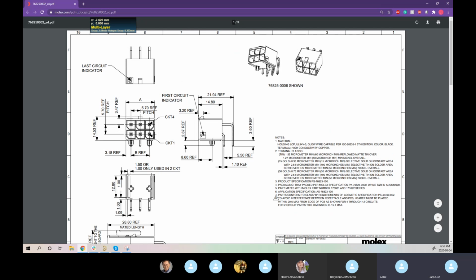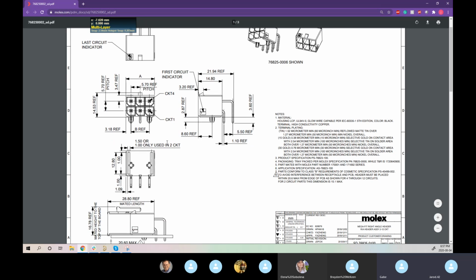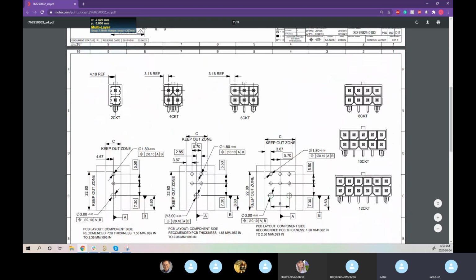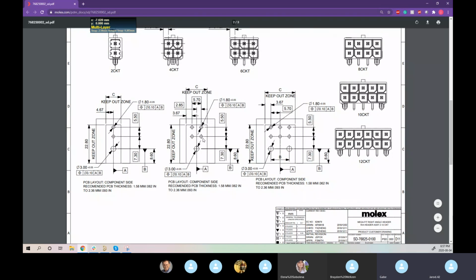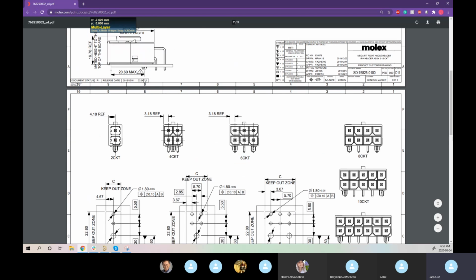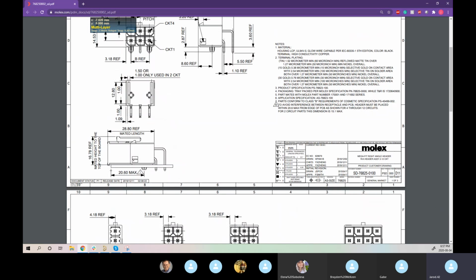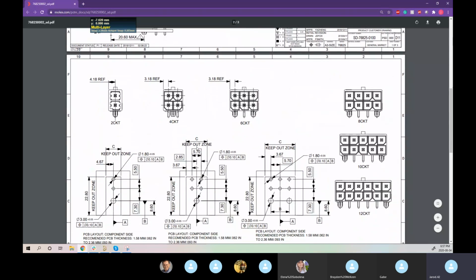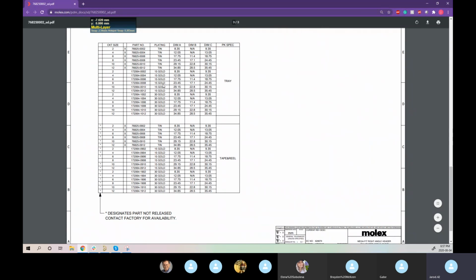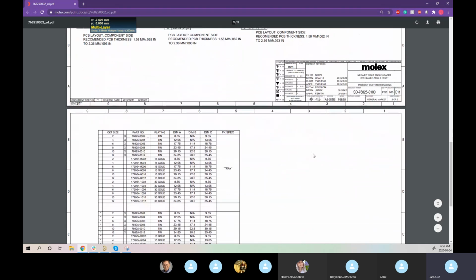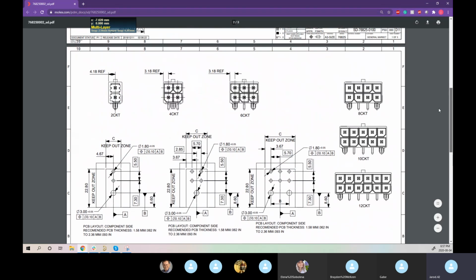So some connectors will have these, and we can see that again, this datasheet that's meant for this 2x1 connector is giving you the pad layout and the reference and the plating and diameters for several different connectors. So you do have to make sure that you come into this knowing that I have this 2x1, so I have to make sure I follow this footprint style.